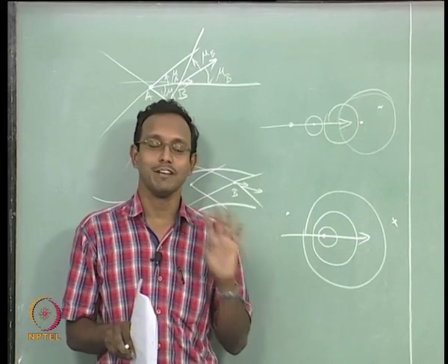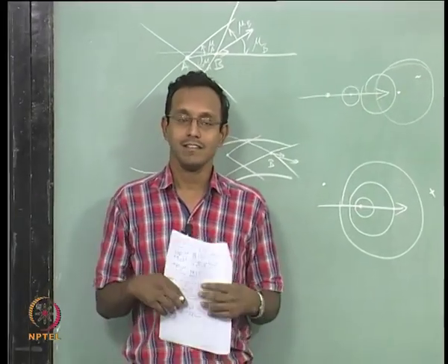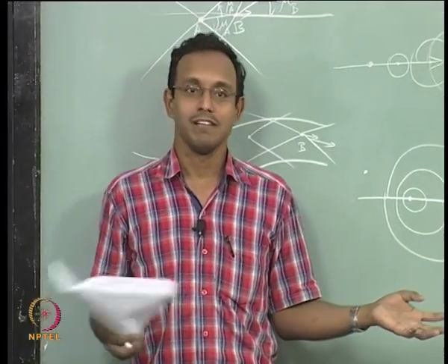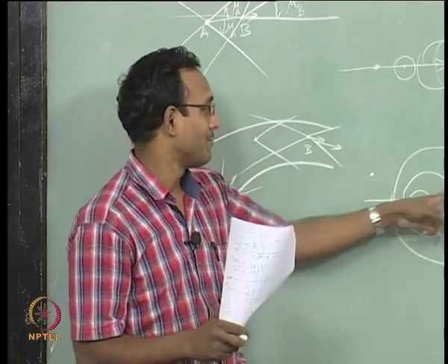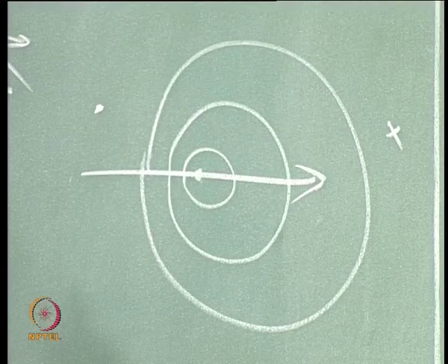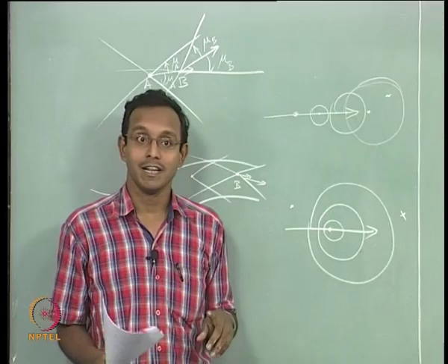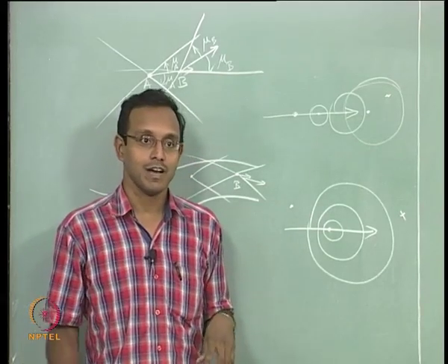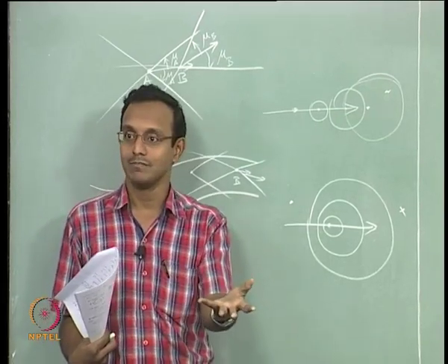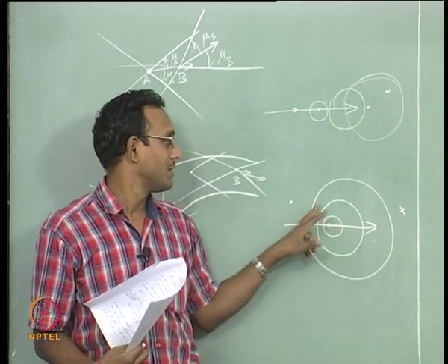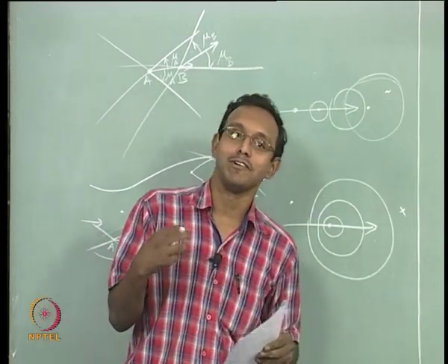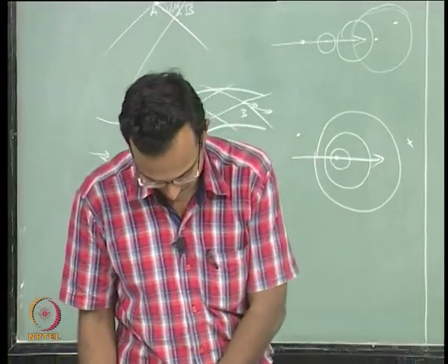When we think about subsonic flows, typically they will say the fluid upstream always knows about what is happening downstream. When they make such a statement, they are assuming they have waited for infinite time, that this wave has already crossed all the points in the flow field which I am looking at. Okay. That is an assumption, remember that. In the unsteady world that will not work. I just now created the disturbance, I did not wait long enough, but I want to see what happened to the fluid. So maybe some points will be influenced, but some points will not be influenced. Okay. So life is a little more complex when we go unsteady. We will look at more unsteady problems later.